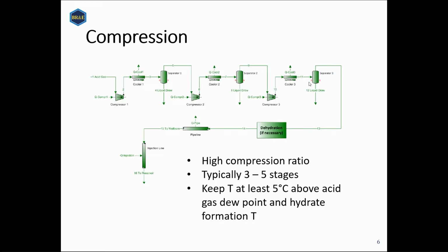And of course, we have the multiple stages to keep those temperatures where they need to be and to keep the efficiency of the process high. With that water removal, you'll also get some protection from hydrates. If you have less water in your system, it's going to be a little bit harder for those hydrates to form. And of course, that's going to help us down the line with the pipelines and injection as well.